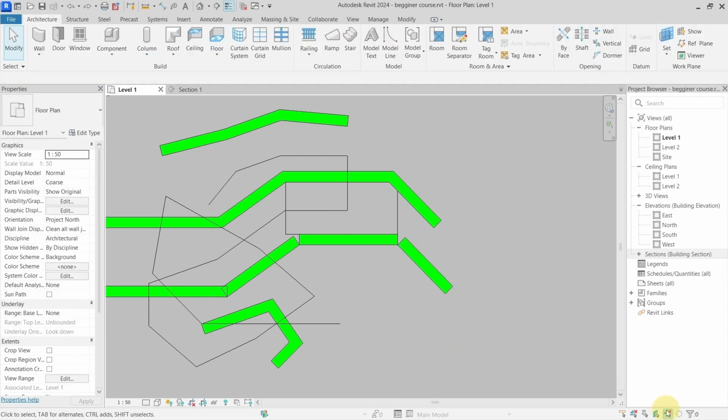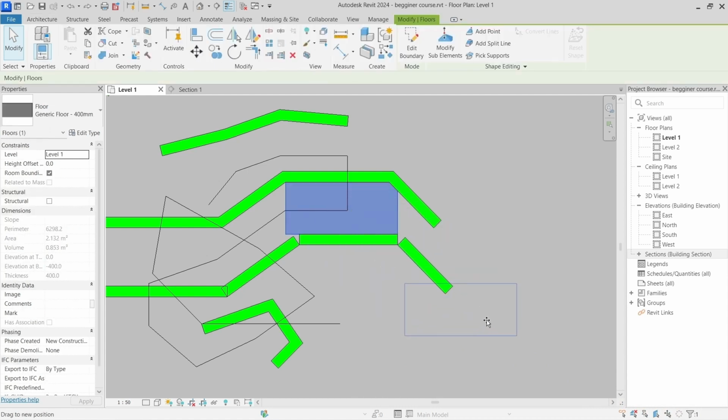But if I try to do the same thing now with this setting allowed, and I start on my floor, and I do the same thing, you can see that I'm not creating a rectangle, but I'm moving my floor away. And this is because with this setting, I do not need to select the element first. I can just drag it on the selection in one go.